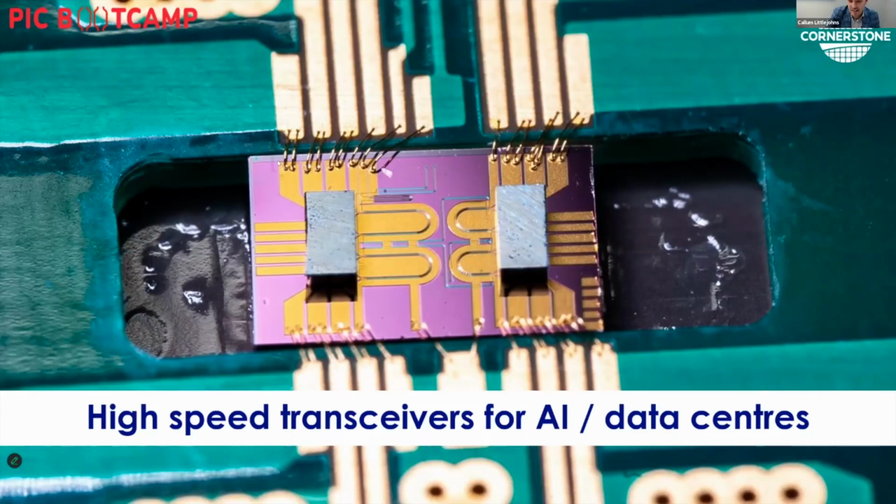What we're looking at on this slide is a photograph of a photonic chip. I'm not sure if you can see my mouse or not, but on top we've got two electronics driver chips that are flip chipped on top of a silicon modulator. And I'll come on to that, but that's definitely a direction of travel that we're seeing, more and more integration of different chiplets, different materials onto silicon.